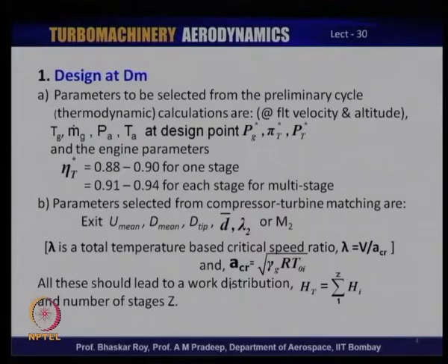The parameters to be selected from the preliminary cycle, which includes factors like flight velocity and flight altitude at which the design point has been selected. As we have discussed, the design point may be ground static condition for an aircraft engine, or it may be a flying condition, especially if it is a supersonic aircraft and engine meant for supersonic flights.